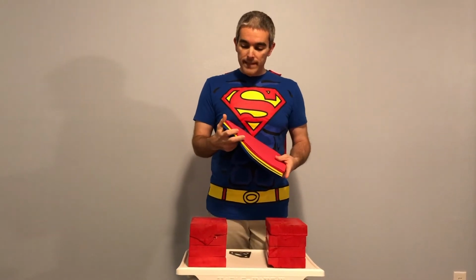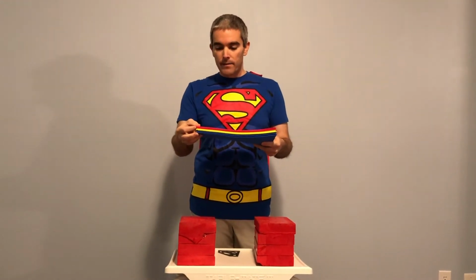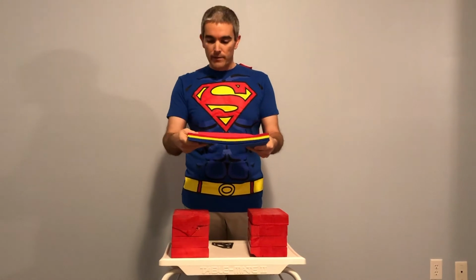Now, a more efficient system is to be able to pass the shear between the layers. In most beams, if it's all one material, like a steel or a concrete beam, then the material itself is passing these shear stresses to each of the layers as we go down through the beam. But if you have a composite system of distinct layers, you need to somehow bond them together. So maybe you use some sort of epoxy or glue.